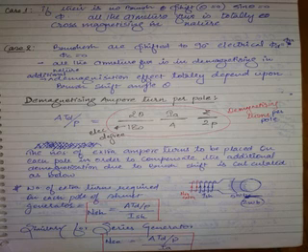Is the point clear? This heading is representing these 2 Webers. Once you read the heading, what is that? Demagnetizing ampere turns. What is ampere turns? MMF. What is MMF giving? Flux. What is that flux? Demagnetizing flux. Is the point clear or not? So that demagnetizing flux you are calculating should be compensated by all the poles, not one pole. It should be distributed. That's the reason why you are calculating per pole.